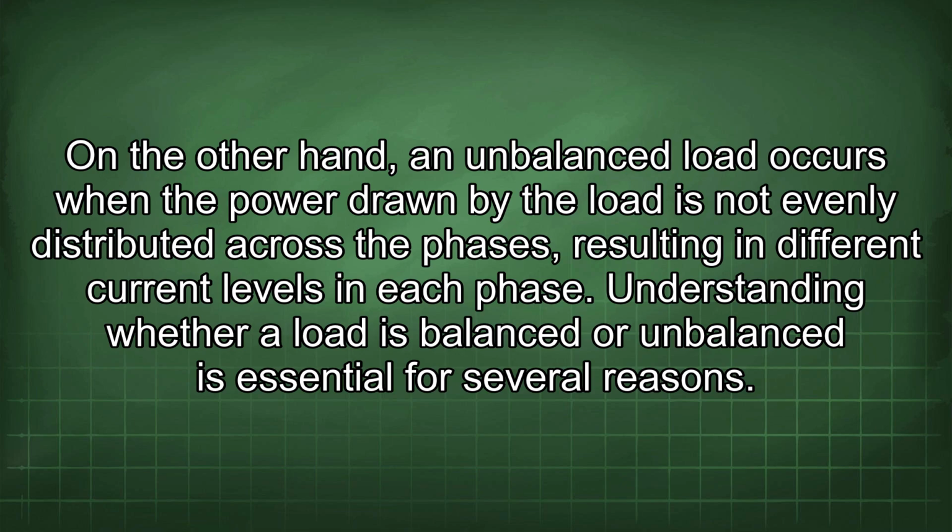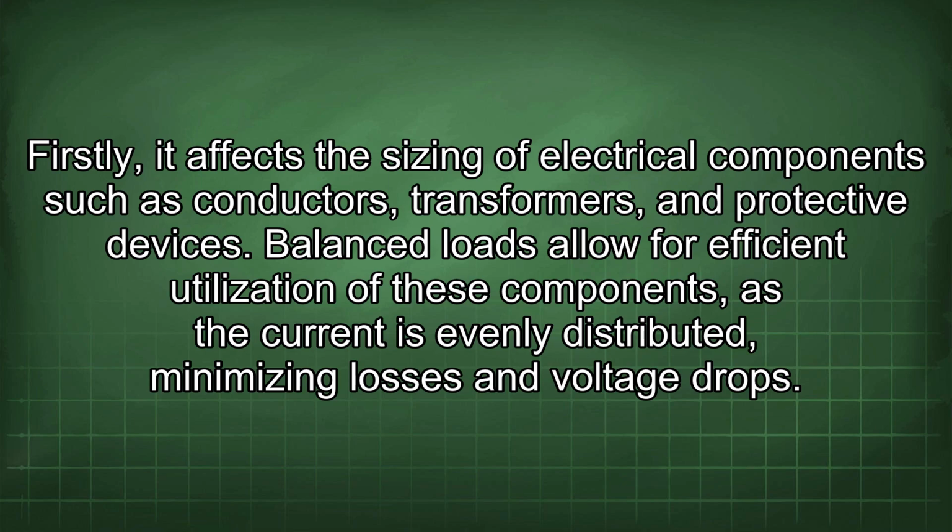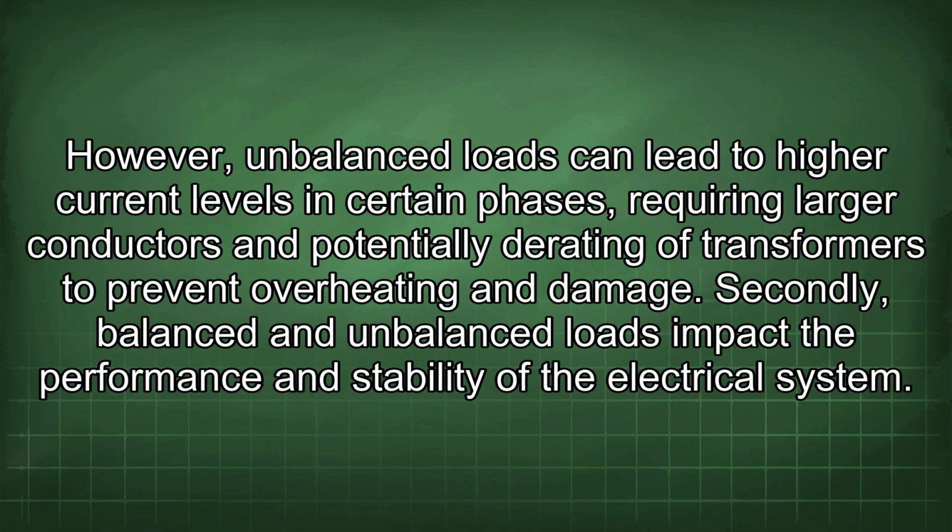Understanding whether a load is balanced or unbalanced is essential for several reasons. Firstly, it affects the sizing of electrical components such as conductors, transformers, and protective devices. Balanced loads allow for efficient utilization of these components, as the current is evenly distributed, minimizing losses and voltage drops. However, unbalanced loads can lead to high current levels in certain phases, requiring larger conductors and potentially derating of transformers to prevent overheating and damage.